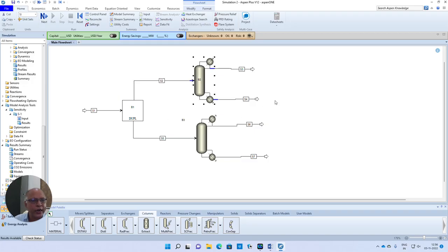Once again, let me concentrate on that. Remember, this is a shortcut distillation design. So in this case, we are specifying the feed stream. We are also specifying the purities of the top product and bottom product, though not exactly mole fractions, but in terms of recoveries, and we are specifying the reflux ratio. Then it was calculating the number of stages, feed stage location, the minimum reflux ratio, the actual reflux ratio, and some other details, reboiler duty, condenser duty, and so on.